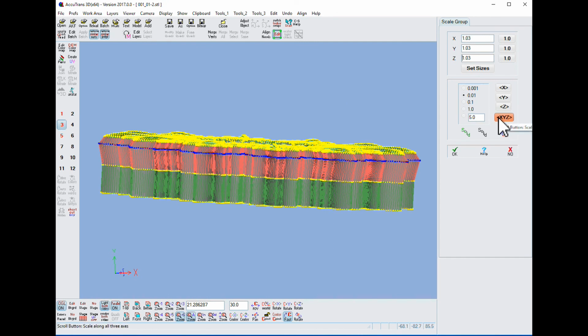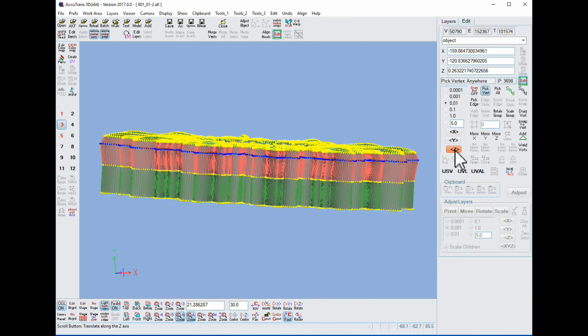And you can just click on either end, do a quick click, and you can move. These radio buttons here control how much we move. It's set on 0.1, so we're moving at a 0.1 increment. So I'm going to leave this scaled at 0.1 and say OK.